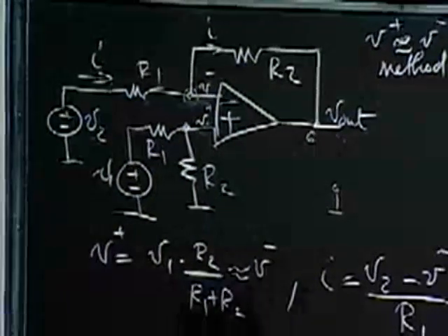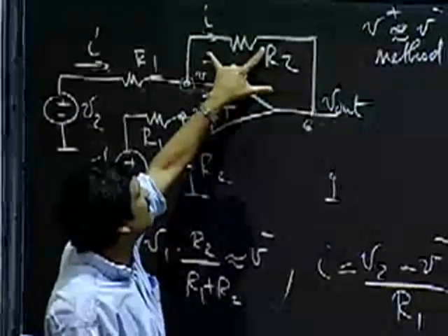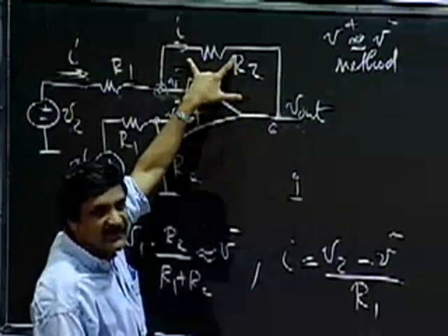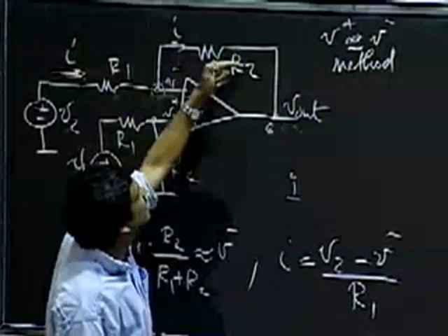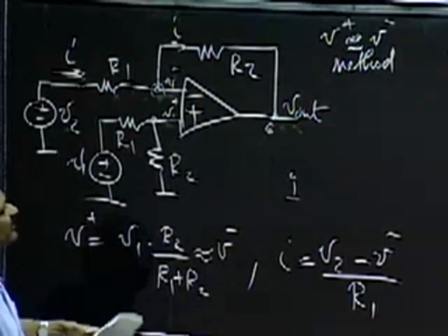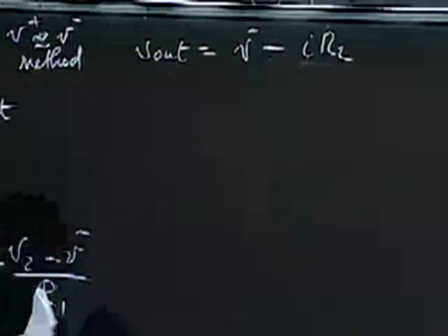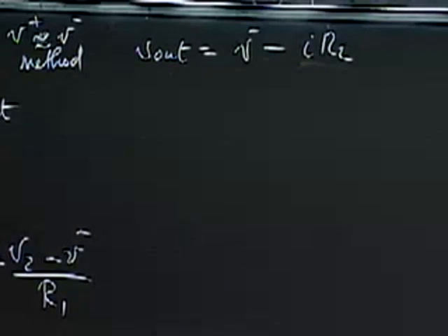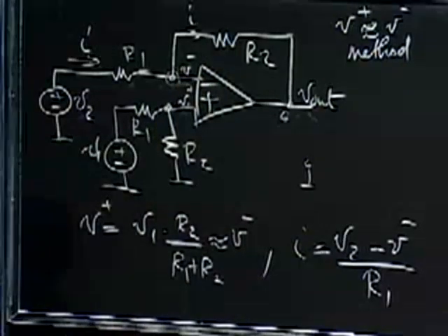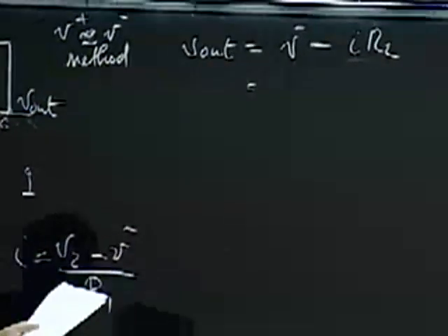One thing to be very cautious about, I'll tell you right now, is that the output here relates to the inversion of the voltage across this resistor R2. Be very, very careful: if I have a voltage across this resistor here, that impacts V out with a minus sign attached to it. Notice that IR2 is the voltage across R2, and V out relates to the negative of that. Be very cautious. That's one of the commonest silly mistakes I've seen people make in solving problems like this.